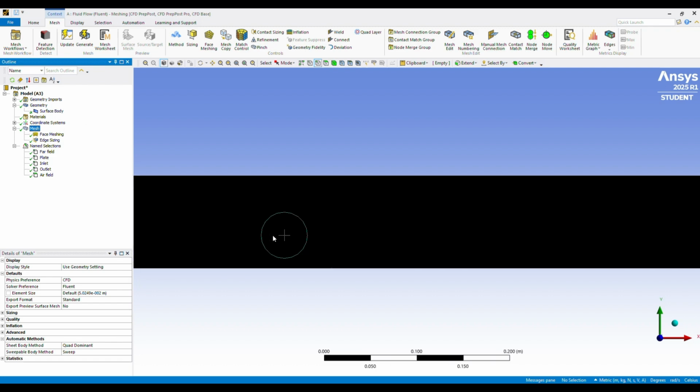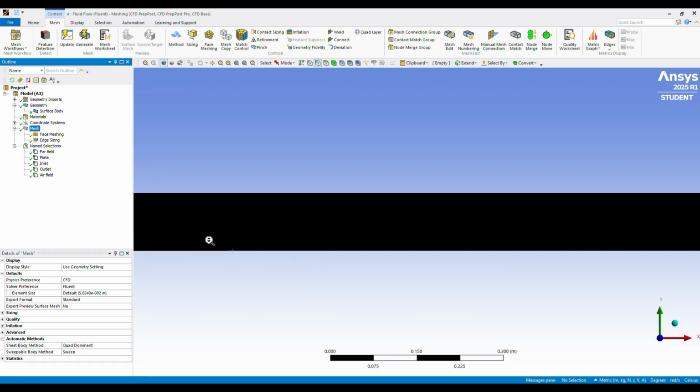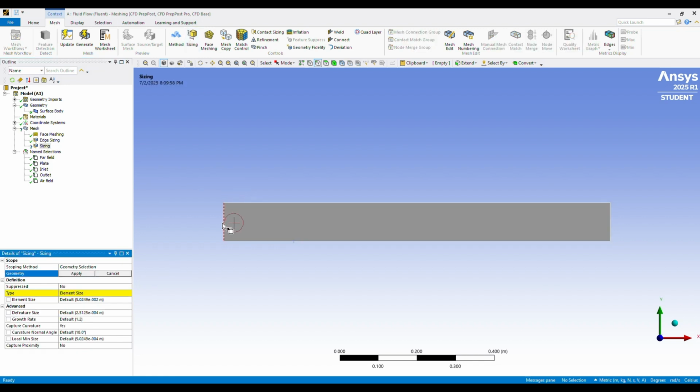And then it's kind of hard to see, but we want to create another sizing mesh on our left and right sides to get a little bit more definition. So we can start with the left side, click the left side, select apply. Same options as before, number of divisions, leave that as so. And then doing the math, you're going to want around 200,000 total divisions. So we can do 200,000 divided by 3,000 that we did along the x-axis. That's going to leave us with roughly 66 divisions. So I'll just go with 70. Keep it a nice number.